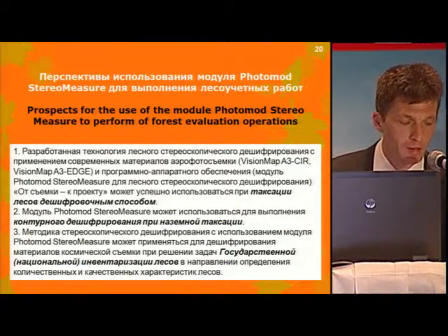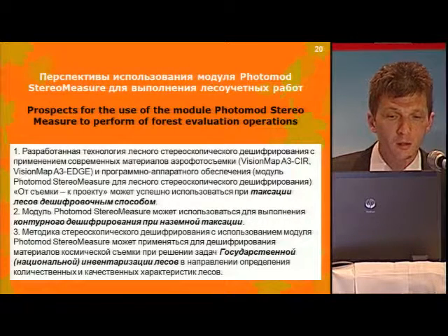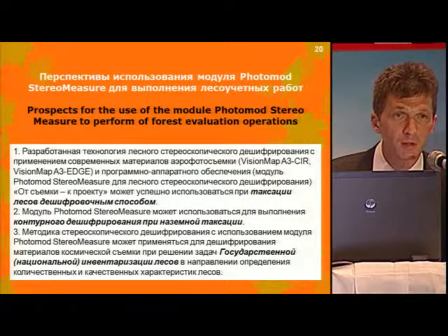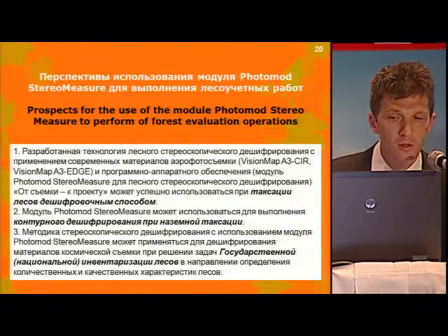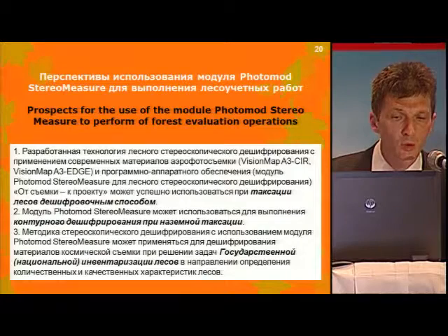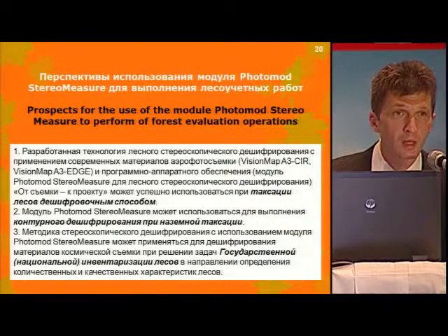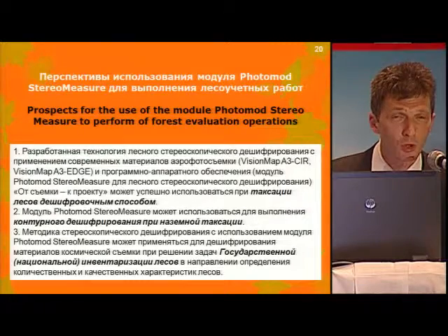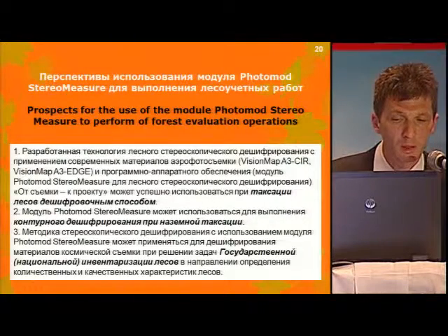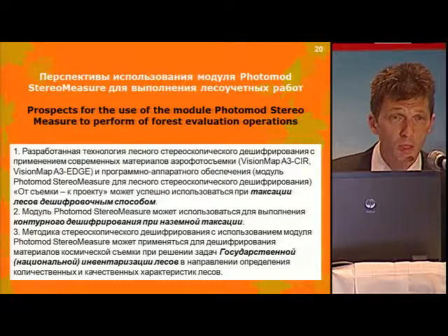And in conclusion, after describing everything that I did, I can tell that the main prospect about the use of PHOTOMOD StereoMeasure for inventory of forests, the technology of forest interpretation based on the materials of Vision Map A3 and Vision Map A3 Edge, and the module of PHOTOMOD StereoMeasure, can be used for taxation of forests, and which we are implementing already for the 2nd year in our daily real projects.